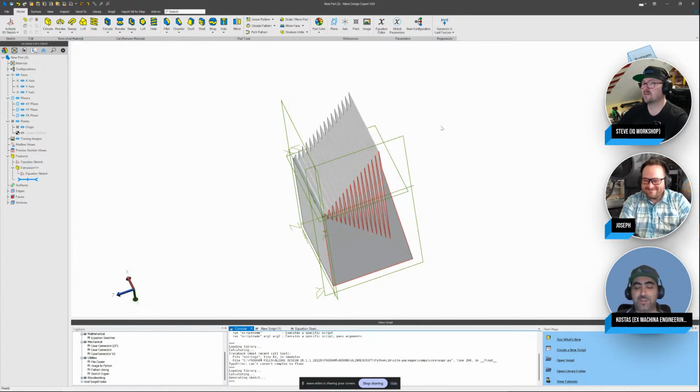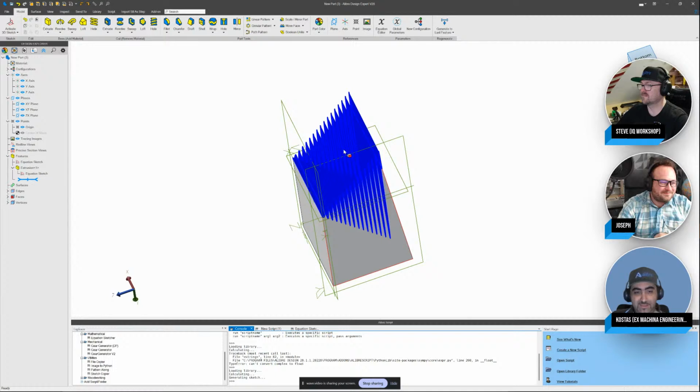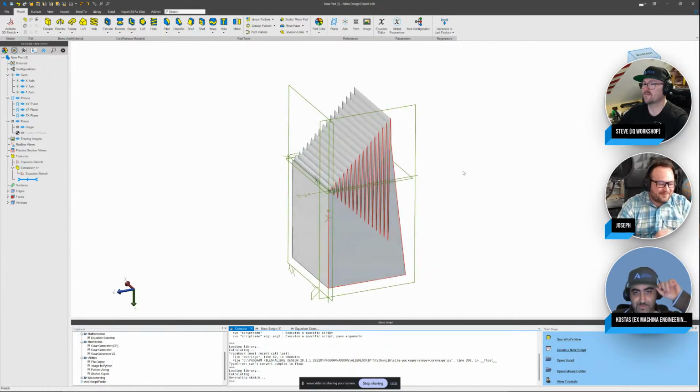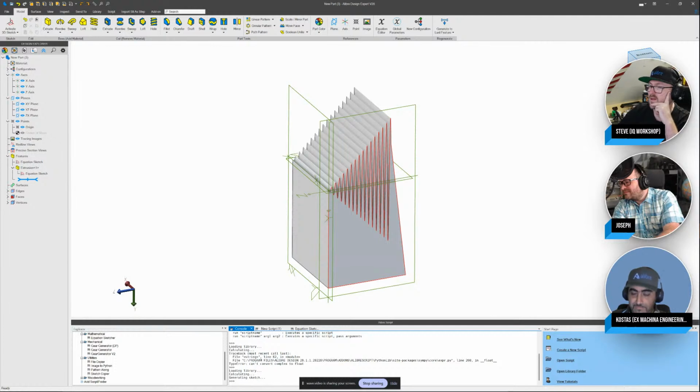So you can do pretty weird stuff, and you can definitely get the third dimension in there going, or control the x direction with one function and the y direction with a second function, which is exactly what you need to draw the involute curve, right, for a spur gear. So you can get that one dimension higher, that equation sketcher, with AI pretty easily. And then you can do some really cool stuff with it. Script in Alibre is really underrated.